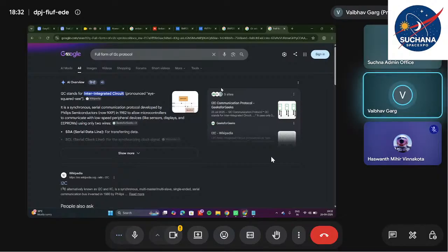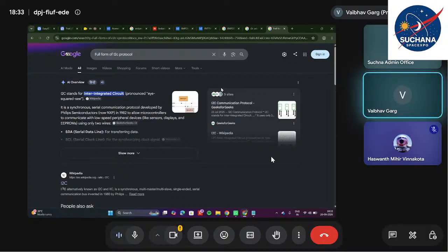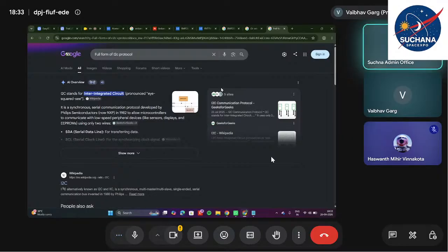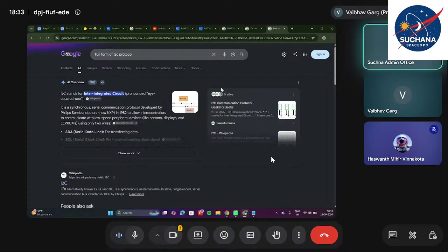In the code it is written that this pin is assigned to this sensor. In the code it is assigned, and moreover there is something called I square C address. Whenever you are initializing any sensor, you used to mention Serial.begin or else something like Wire.begin. Have you ever used that in embedded C? Yes, Serial.begin. Serial.begin is a different thing, for getting output in the serial, I mean in the console port. So there is something called 0x76 or 0x77. You might have used those kinds of values in programming any sensor. Have you ever, at least have you ever observed?